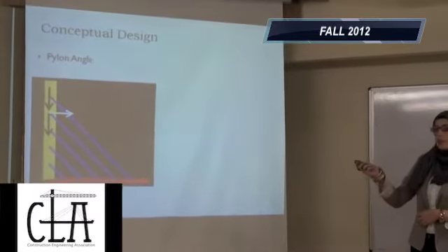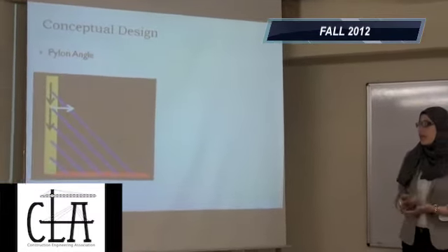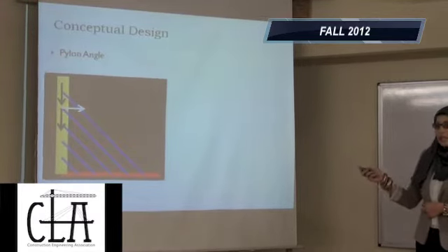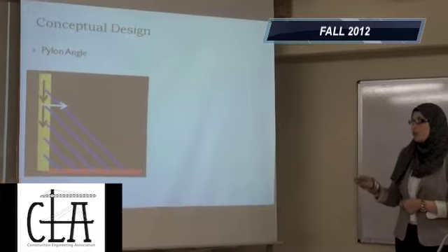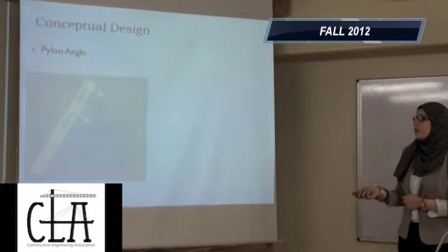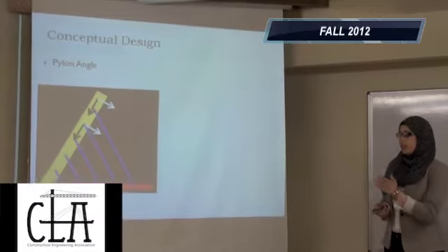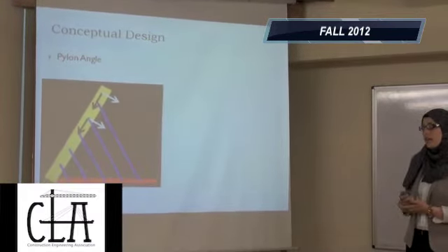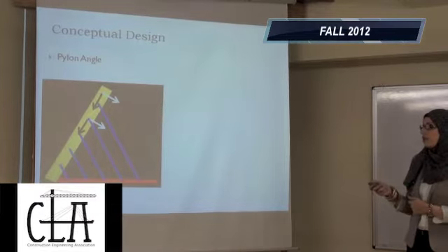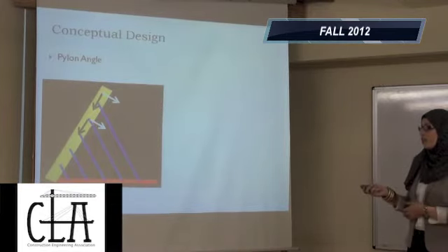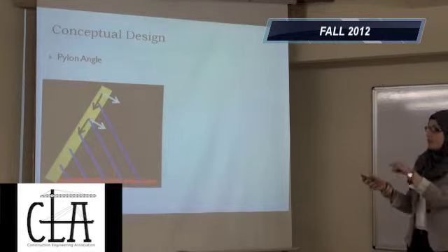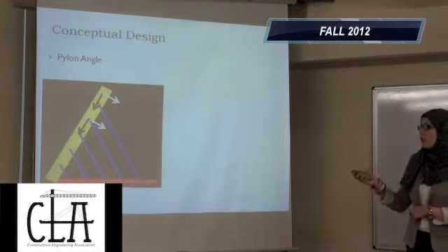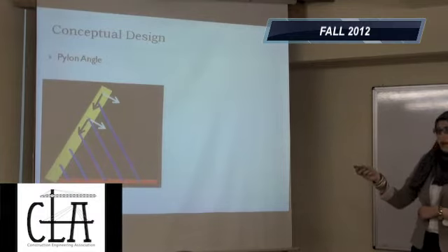The first case, when the piling is vertical, which is the regular cable stay, the horizontal component of the resolution of the tension cable will produce a huge moment, and this is undesirable. The second case, when the piling is inclined inside, we will have shorter cables, and they will sag less, and they will have less tension. But unfortunately, we'll have a huge moment because of the transverse resolution of the tension cable and the transverse resolution of the whole weight of the piling.